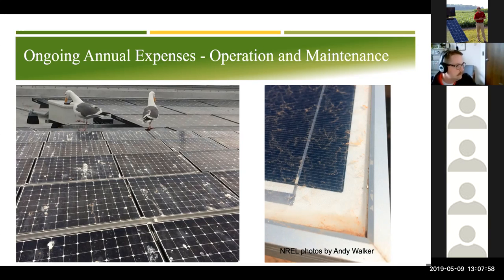So think about a ground mount system on your farm. If it's near a field and you're shelling corn or taking off soybeans, it might be worth going out to give the panels a good cleaning if there's no rain in the forecast.